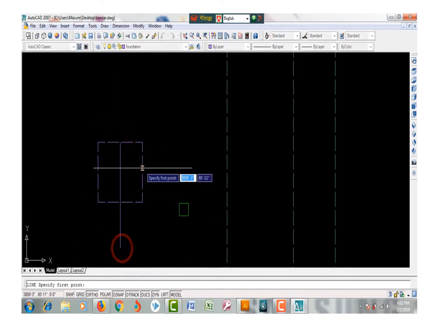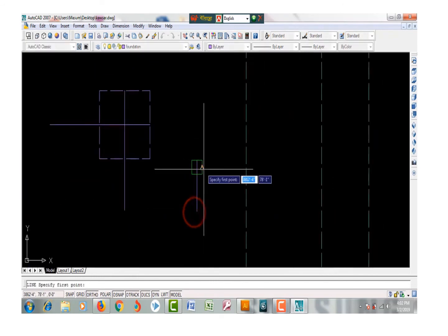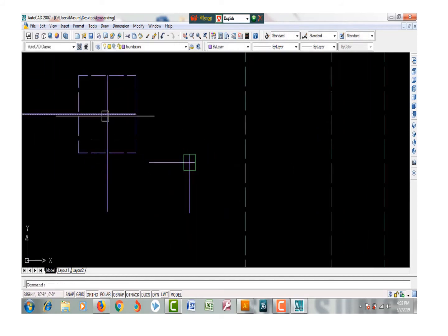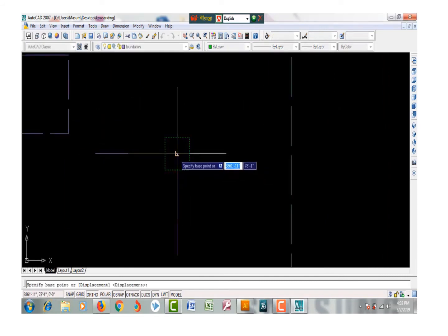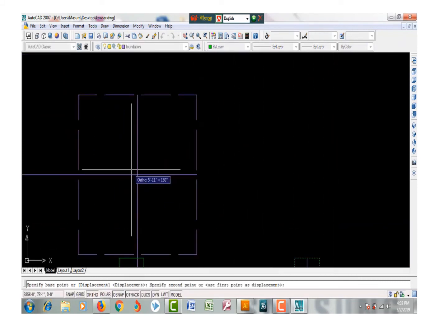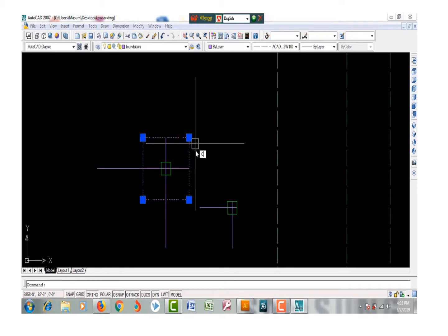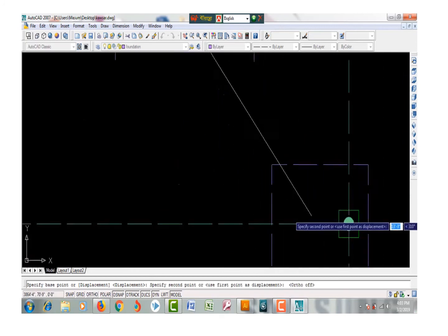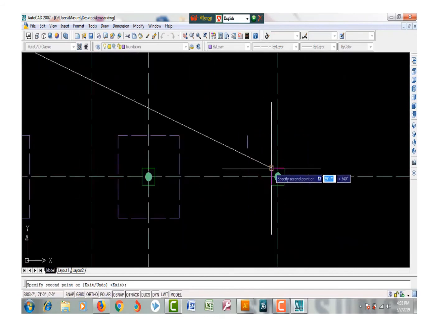Some 100 mm offset can be provided at the two sides beyond the size of my footing slab, so that we can keep the concrete comfortably within the excavation pit. I place the center of a column to the center of the footing in the given arrangements.